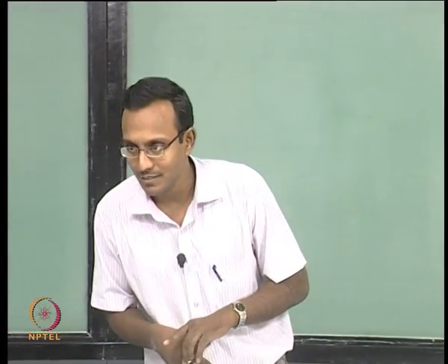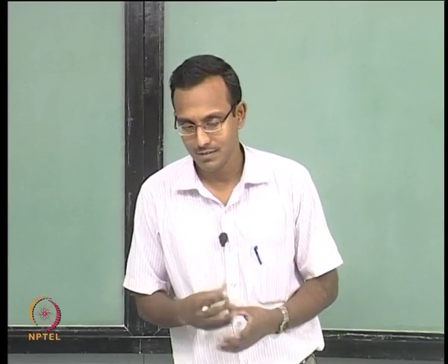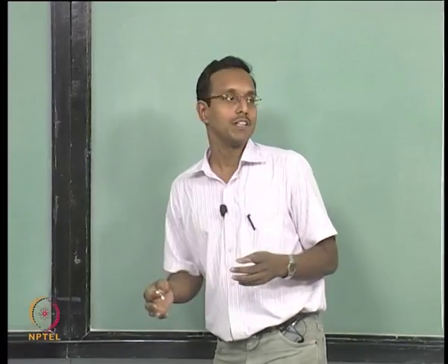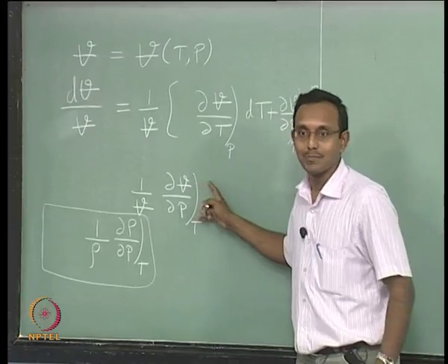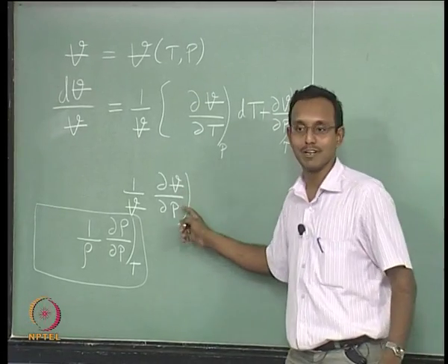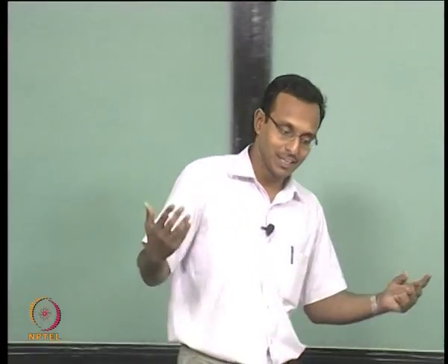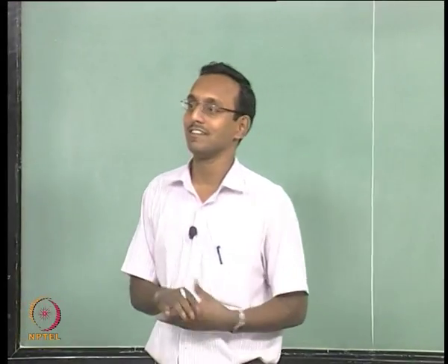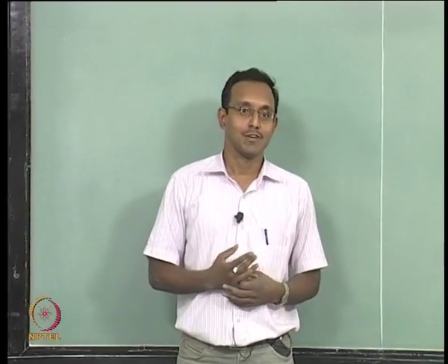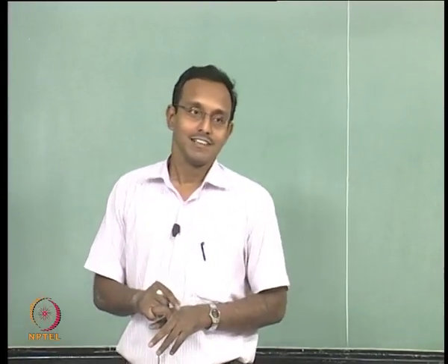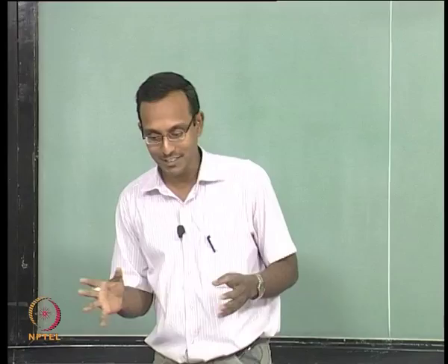We can define this compressibility in terms of bulk modulus of elasticity. Yes, in a way the bulk modulus is related to this term. We can express this in terms of bulk modulus. That is one way of doing it. There are other forms, as in terms of velocities. There is one way of defining a compressible flow, which is Mach number related. We will keep that in mind, and we will come back to it after some time, and I will just tell you roughly what it means.